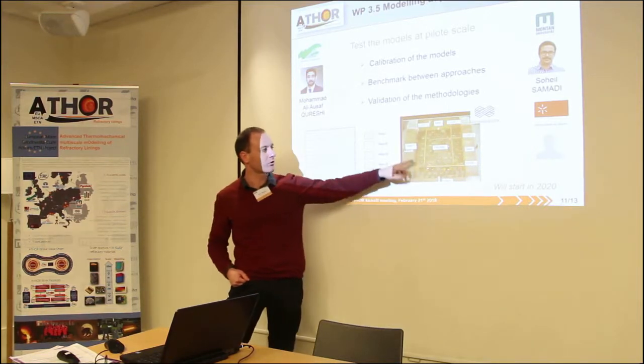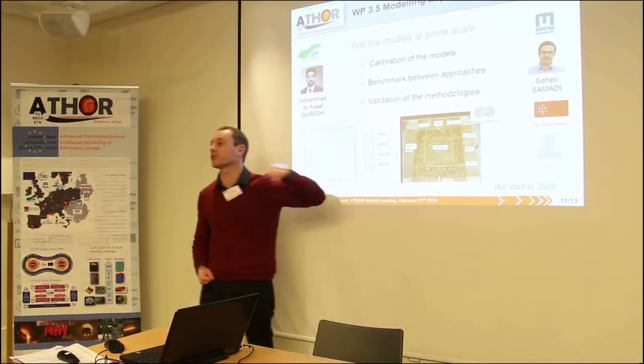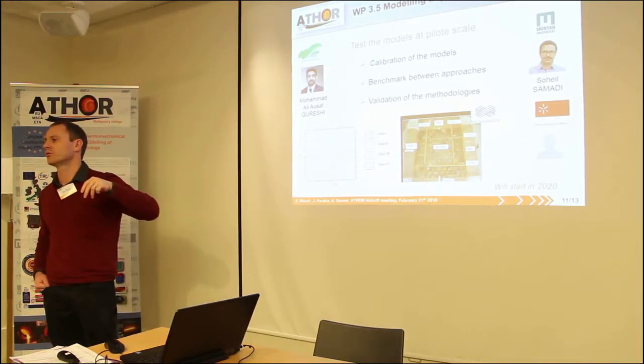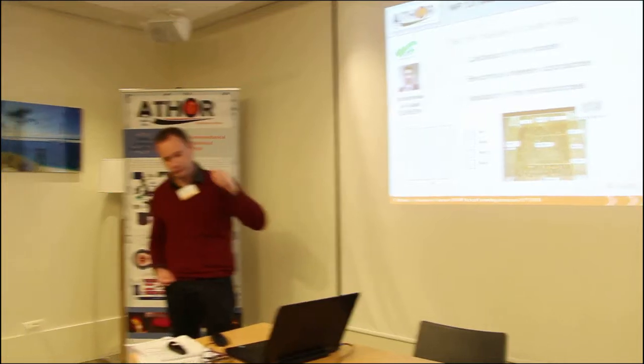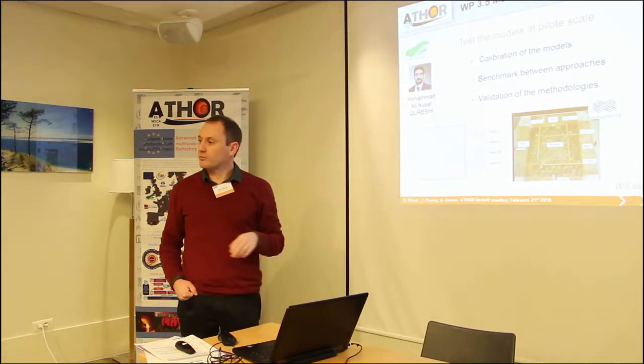There is mechanical load, so it's a big axial compression, and possibility of thermal loading too, up to 1,400, 500. We have to check this. Okay. The mechanical load is not the biggest one. If you are doing it with 1 by 1 meter, then the load is limited to, I remember, something like 1 Newton per square millimeter.